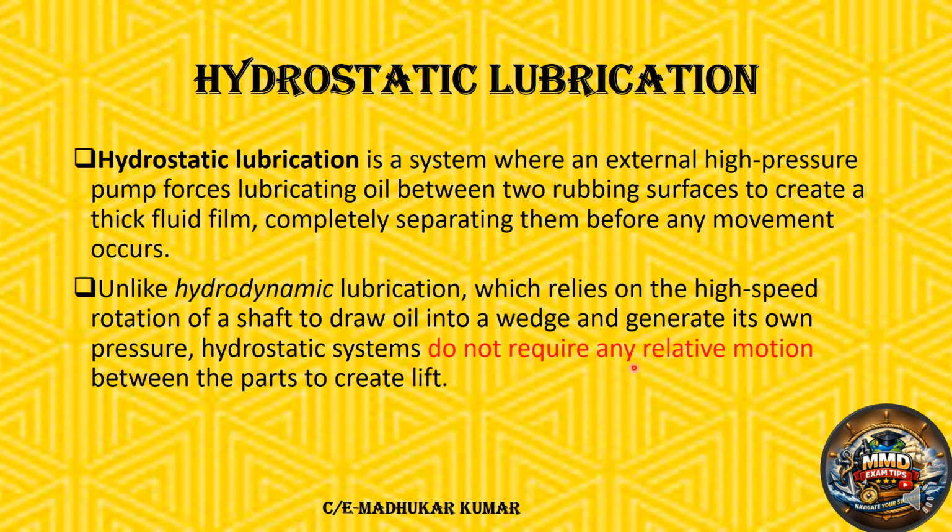This is the most important point. It does not require any relative motion between the parts to create the lift. Lift means the separation of the two rubbing surfaces, journals, bearings, and so on. So it creates the separation due to the pump pressure.